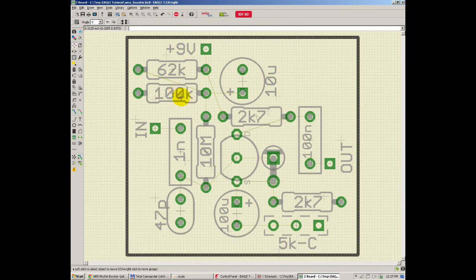Just arranging a little bit here and here, and that should be it. So we are going to start and route our signals. First, I like to start and route the obvious ones, especially for this simple project, the signals that are in straight lines, that are closer to each other, and after that I will solve the other issues on the run.